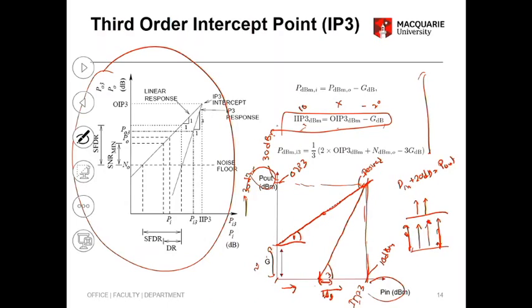Now the questions, you can form the questions in such a way that, so what is your IMD at, say, 7 dBm? How do you work that out? Any guesses? Okay, so I'm going to do it slowly. Okay, so at 10 dBm, you are 30 dBm out, right? That is output power plus your IMD power, 30 dBm.